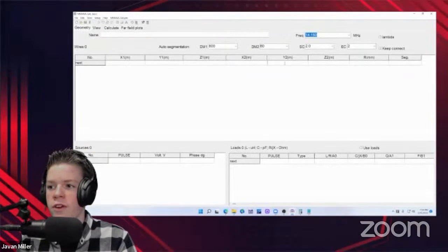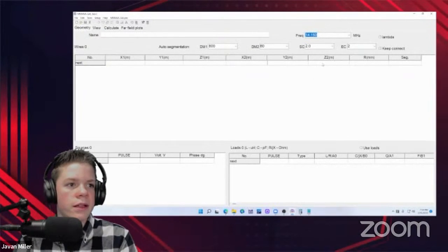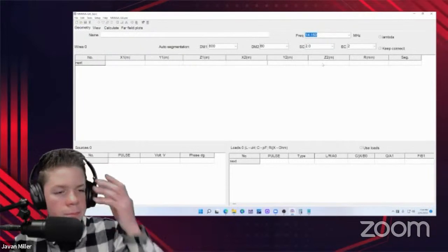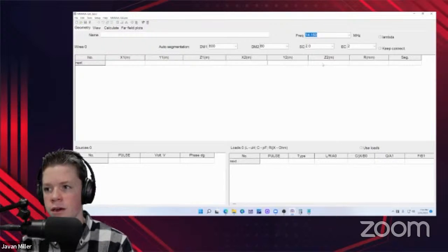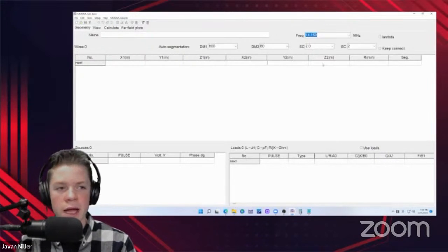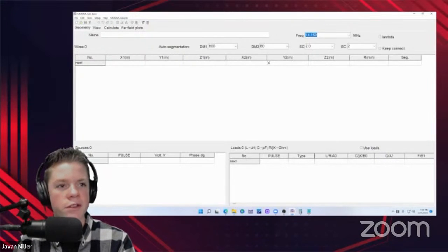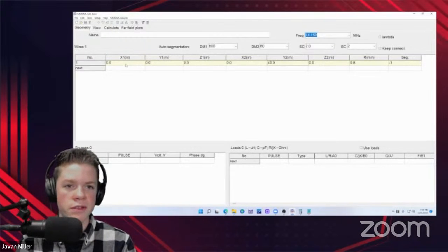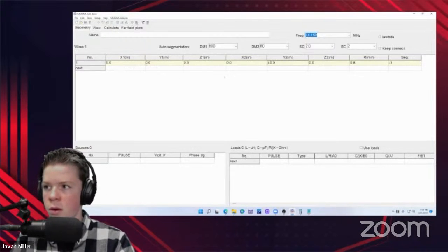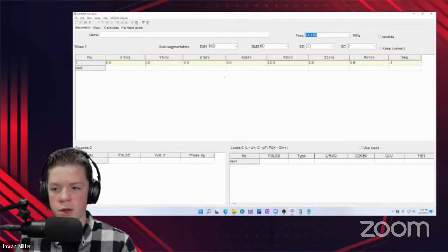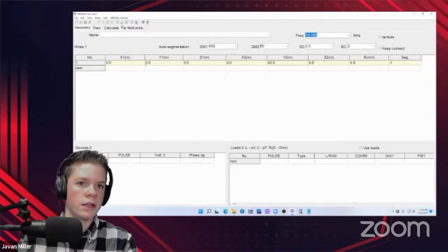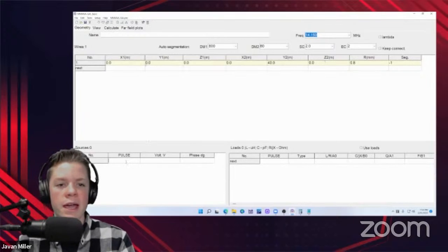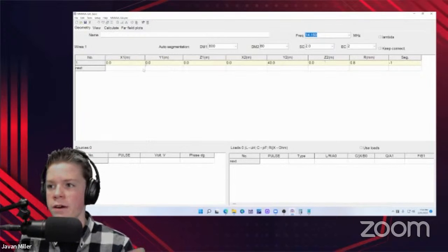Okay, so that'd be more of a random wire antenna. I see. All right, so we're just going to do an end-fed half wave here for 80 meters. That would be around 40 meters long. So again, this is 0, 0, 0 for the XYZ coordinates for the first point, and 0, 40, 0 for the second point. And then let me add a second wire as a counterpoise.